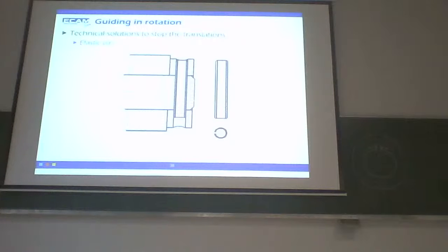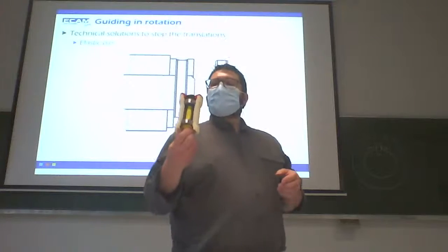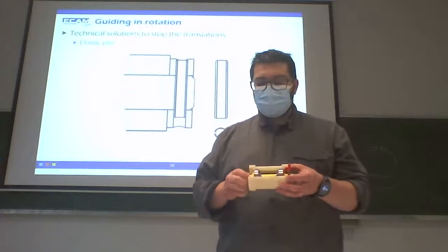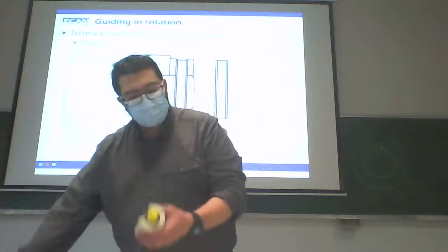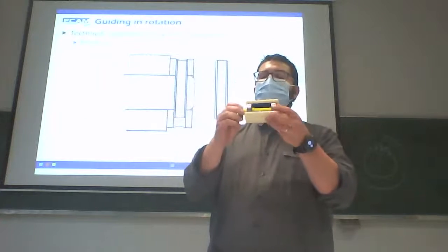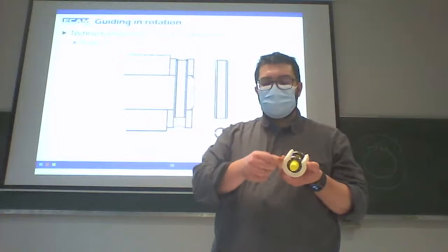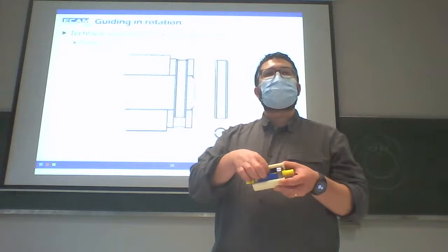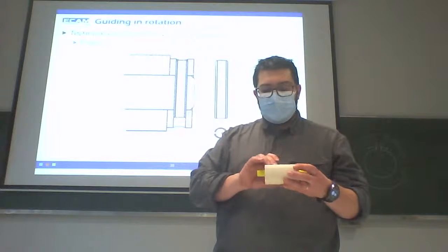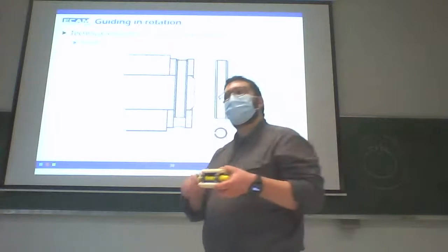First example. Second one. Here I will use an adhesive. Here I will glue a cover to stop the inner ring. In blue is an external spacer, and I have a shoulder on the shaft to permit the rotation.